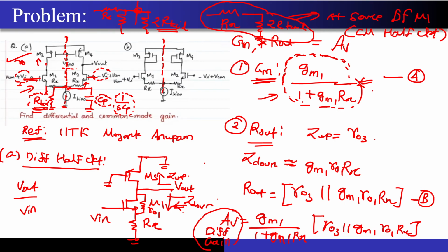I have some impedance looking down. What will be my voltage at this particular point? So you can still apply the formulas and short methods that we have seen, but you need to literally consider V and minus V and then calculate the values of Vx and Vy at these nodes, then subtract both of them, and you will get the voltage gain of the circuit.